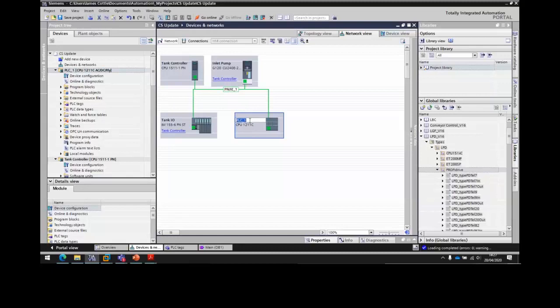Of course, if we're looking to use PUT and GET, we have to turn off one layer of security that's built into the SIMATIC controllers to allow some random thing to be putting and getting data out of the controller. So a better way of doing this would be by using Profinet communications instead. So let's say in my application, I've now added an S7-1200. Maybe this is controlling the heater on my tank with its integrated PID control.